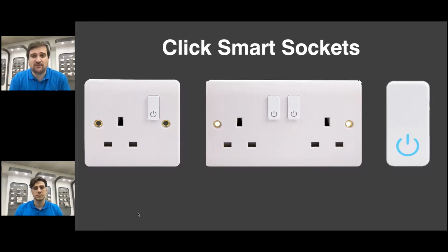To switch these into pairing mode, you turn your gateway on, put it into pair mode. You then press this black button there, any one of the rockers, for 5 seconds, and it starts to pair almost instantly. You'd fit it exactly the same as any other standard 13 amp socket.